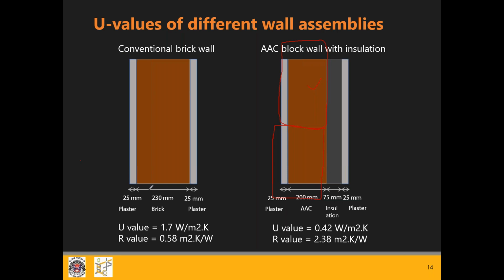Like if you want to do a cost analysis, one of my criteria is that I should be ECBC compliant, and second, I need to have a cost effective building envelope as well. So you can vary these things. In one scenario you can see, if I have an insulated wall, what would my U value be?